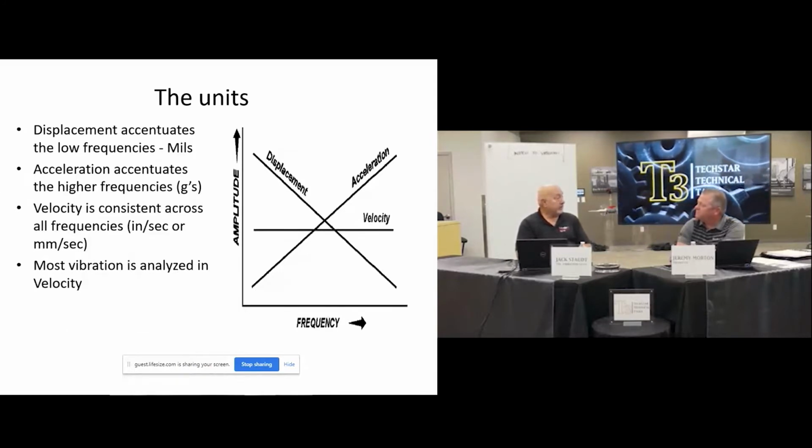And if we have to really look through the data with a microscope, we can change things to displacement or acceleration, whether it's unbalance or even subsynchronous type frequencies, or we're looking at gear mesh frequencies with sidebands. We'd probably want to look at acceleration. So velocity is kind of that middle ground. You can cover some of the displacement applications, and you can cover some of the acceleration applications. Absolutely. And like you said, if you're on a gear mesh type application, obviously you'd probably use an accelerometer for more in-depth analysis on those higher frequency applications. That's correct. Gotcha. Yeah. All right.